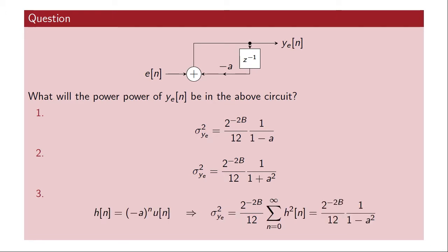And one can of course also do this explicitly by working out the impulse response of this system. So the impulse response of this system is a simple AR tapering off with this constant a here. So this would be the impulse response of an AR1 system, and once you take the squared magnitude, you get a to the 2n, which you sum up and you get this expression through an explicit computation.